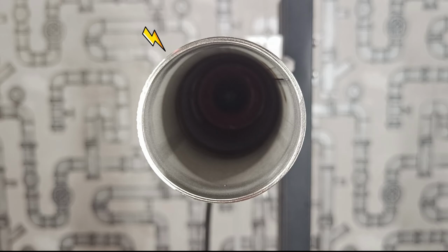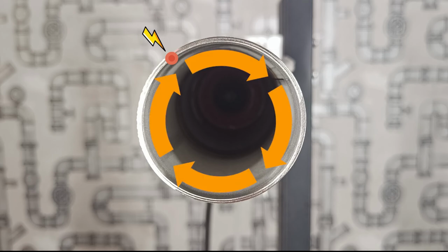Start welding pulse: always set the start welding pulse half a second longer than the gas pre-flow. Start delay: set the wait time for the material to heat up adequately. Rotation speeds: divide the pipe circumference into 4 sections with different speed settings. Overshoot: set how far beyond 360 degrees the welding should continue.